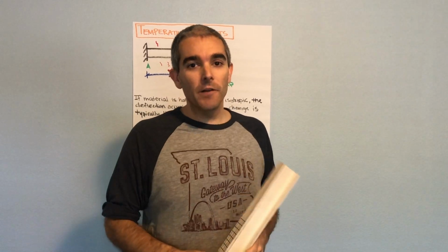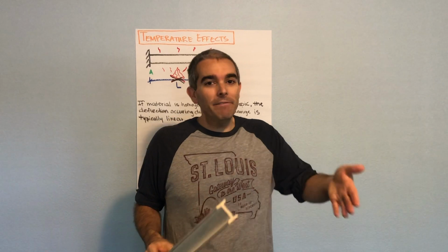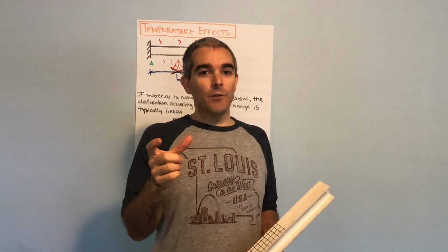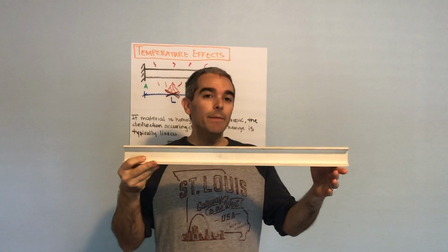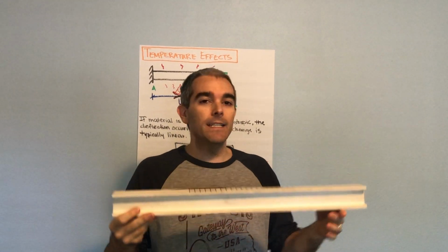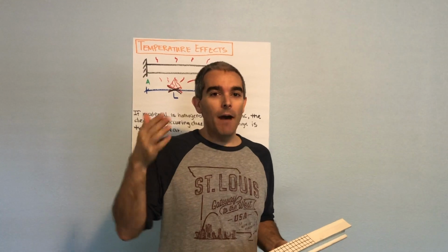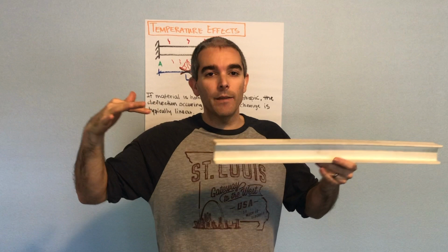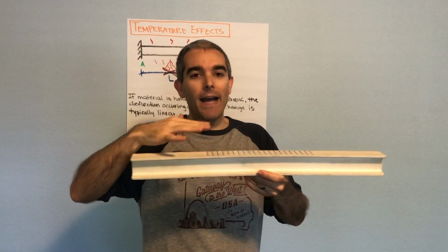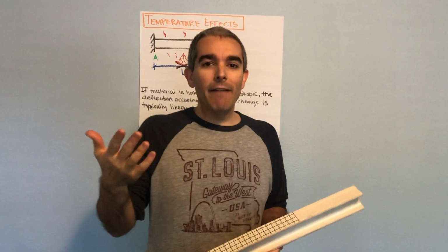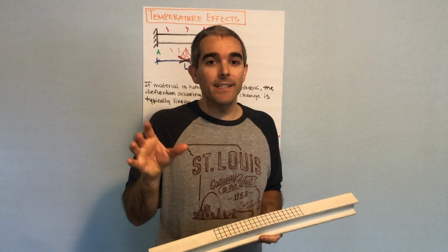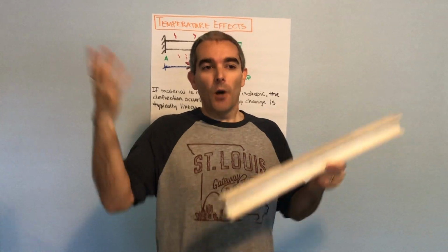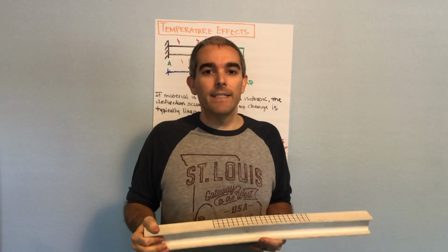If you've gone over a bridge or two in your life, you probably have noticed that a lot of times when you approach the bridge span, there are expansion joints. Because the beam can move back and forth across these rollers, we have to accommodate that in the deck. So we have these expansion joints to allow the bridge to separate and come back together so that we don't have to worry about these large stresses due to temperature changes, and then our beams can just be focused on holding up the load that they're designed to support.